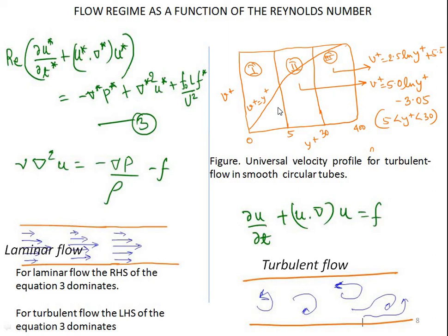But in turbulent flow, of course, we do not have just one turbulent flow. There are 3 separate layers. We see a turbulent flow flowing over a flat plate. So we are having a viscous sublayer. We are having a buffer zone which is represented by zone 2 there, and we are having zone 3 which is turbulent flow, where the flow is fully turbulent.